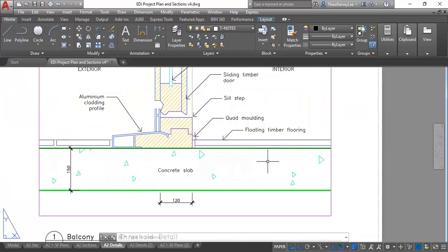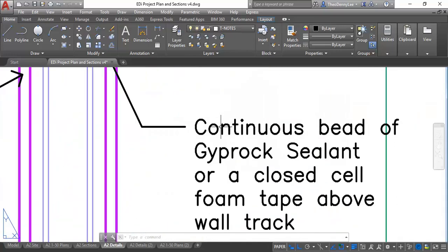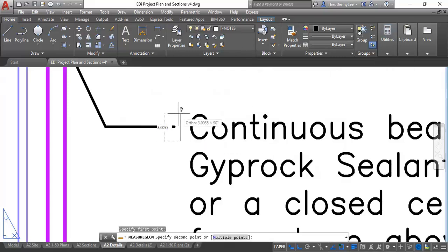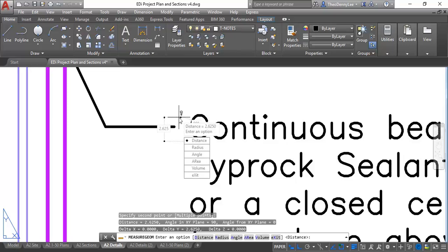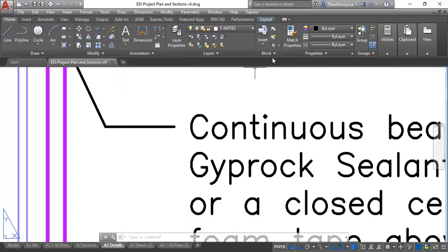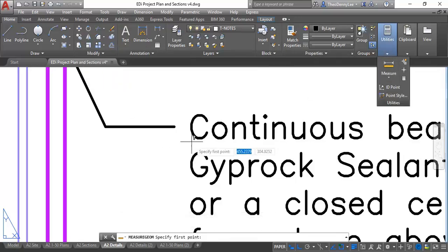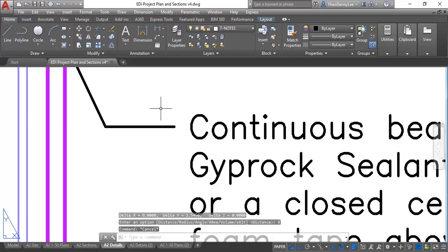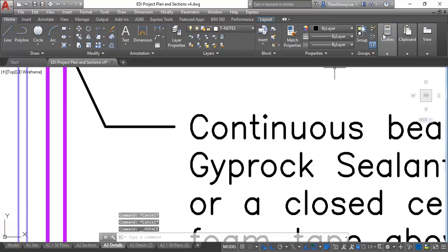So if I measure any text that I've just made using the measuring tape, I can see the size it's going to print. So for a 1 to 50 drawing, the annotations for that would be what size then? Still 2.5 times 50, so 125. And I'll prove that to you. So I've measured this here on the sheet, and you can see 2.5 high. But if I then just switch to model and then measure it again,